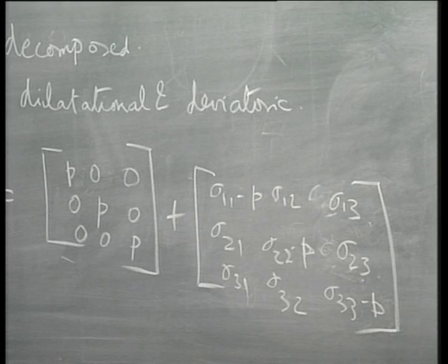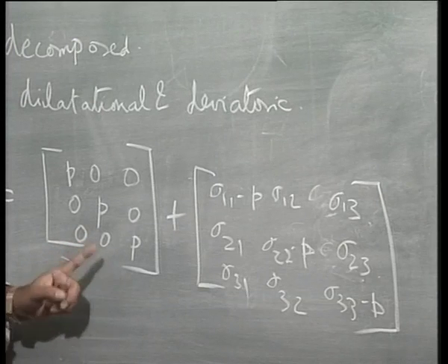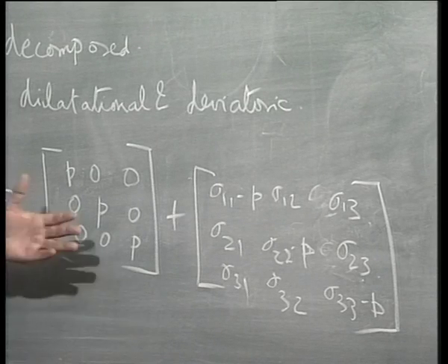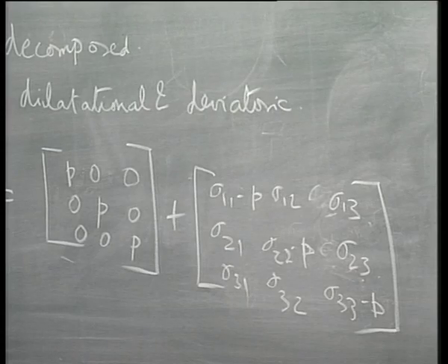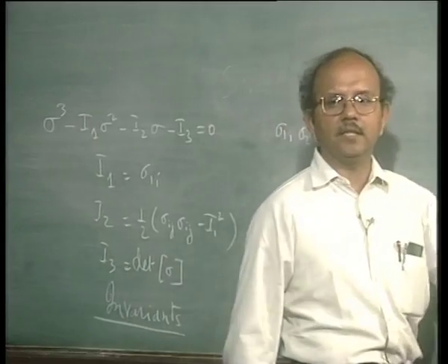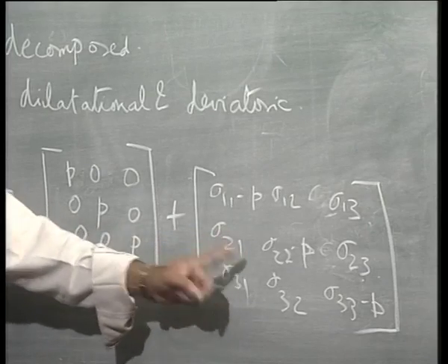In other words, yielding is not signified by the hydrostatic pressure which is superimposed on the deviatoric part. That is how we arrived at it empirically, by a number of experiments. Is that clear?